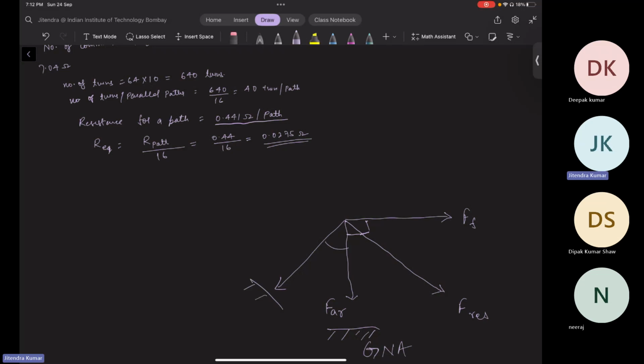So this will have to be MNA, magnetic neutral axis, such that the resultant flux will not affect those brushes, right? So those brushes should be 90 degrees to your resultant MMF, and this direction will be in case of generator. So you have to rotate. Let's say your generator speed is in this way. So you are rotating the rotor in this manner.